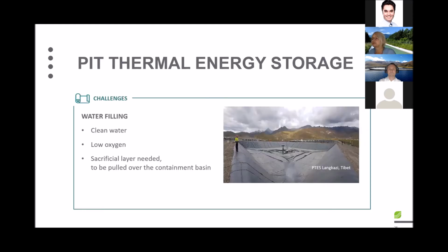Another challenge to be addressed is the water filling of these applications. The water has to be clean. This is essential for the functionality. There shall be no change in the water quality, so it has to be covered during the filling stage. A chemical is introduced to reduce the microorganisms and to reduce the oxygen content. However, what is to be addressed is that the oxygen content in the water is reduced with rising temperature, and it is also reduced by this chemical, which is in principle a salt.